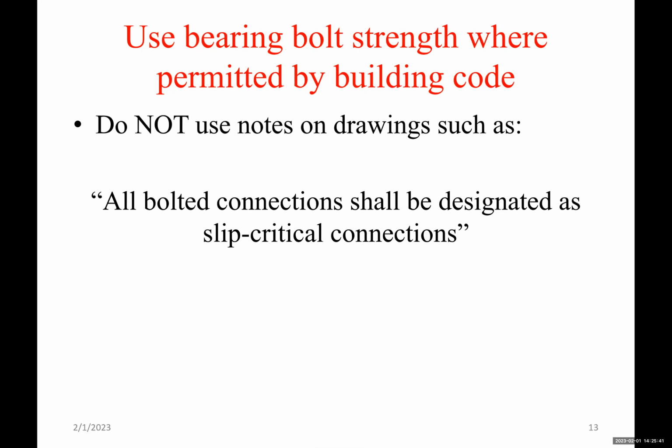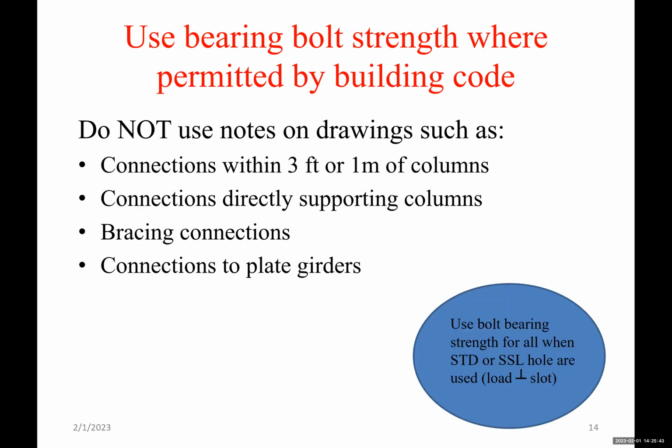Do not use notes on drawings such as connections within 3 feet or 1 meter of column, connections directly supporting columns, bracing connections, connections to plate girders.